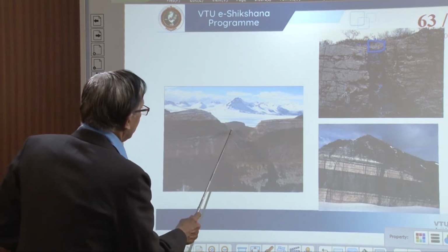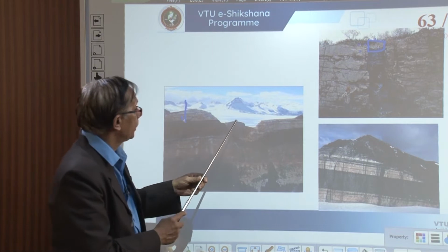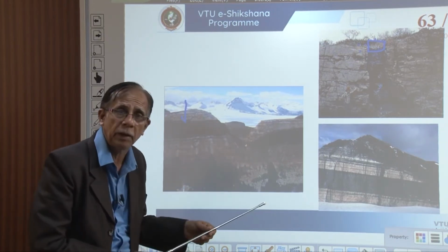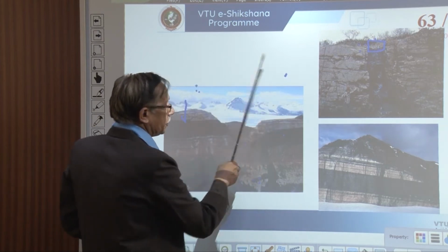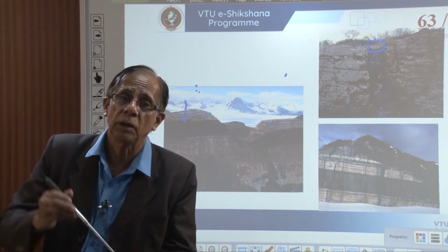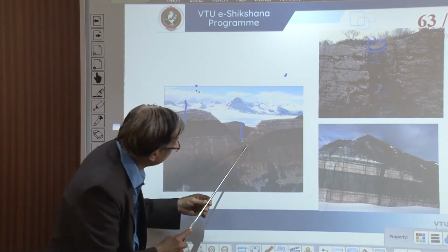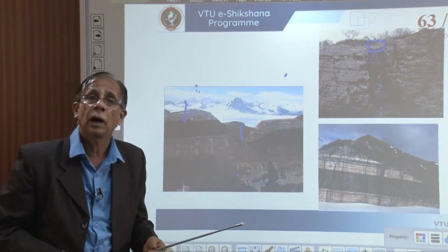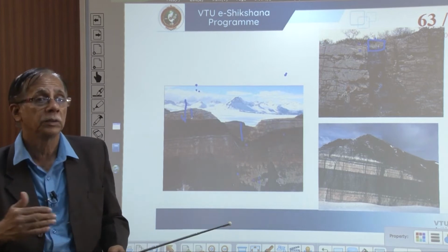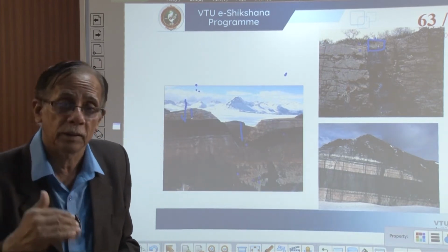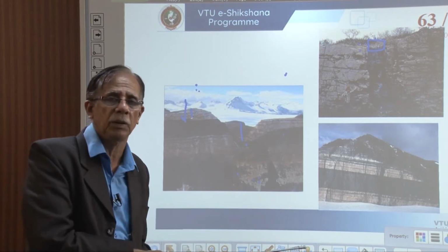This is a sill, again this is a sill. If I have a sill at this depth, I may find it here at a different depth, depending on some kind of subsidence through which the rock material may have moved down. For example, if I have to excavate 100 meters to reach this rock, here if I go 50-60 meters, I am able to reach this rock body. My excavation cost is less here, and more there. Although they were sills and should have uniform properties everywhere, cost varies because of later phenomena.